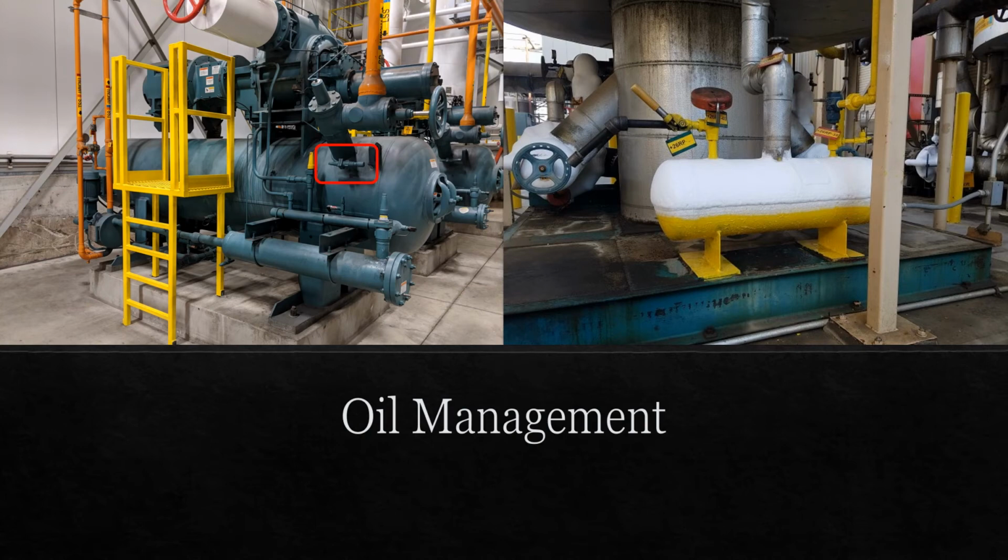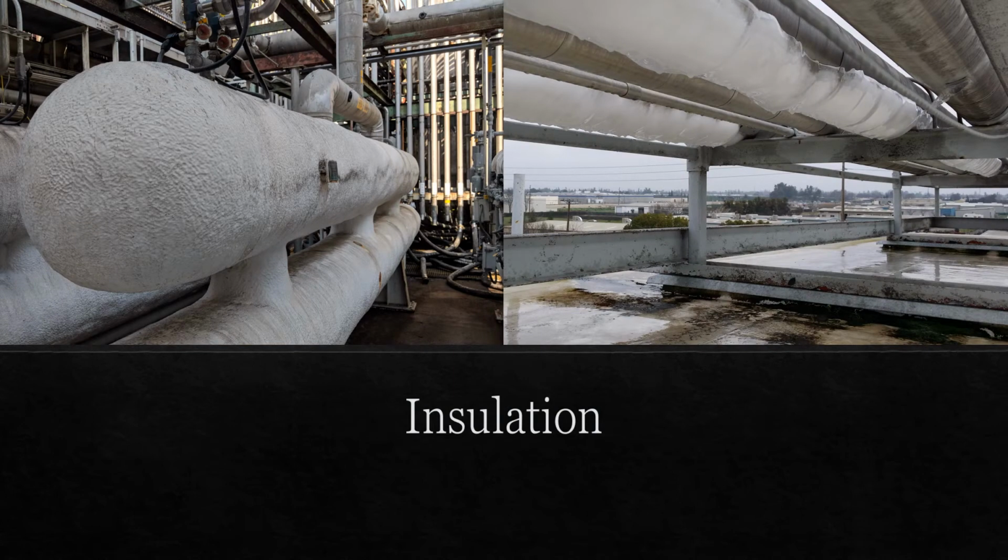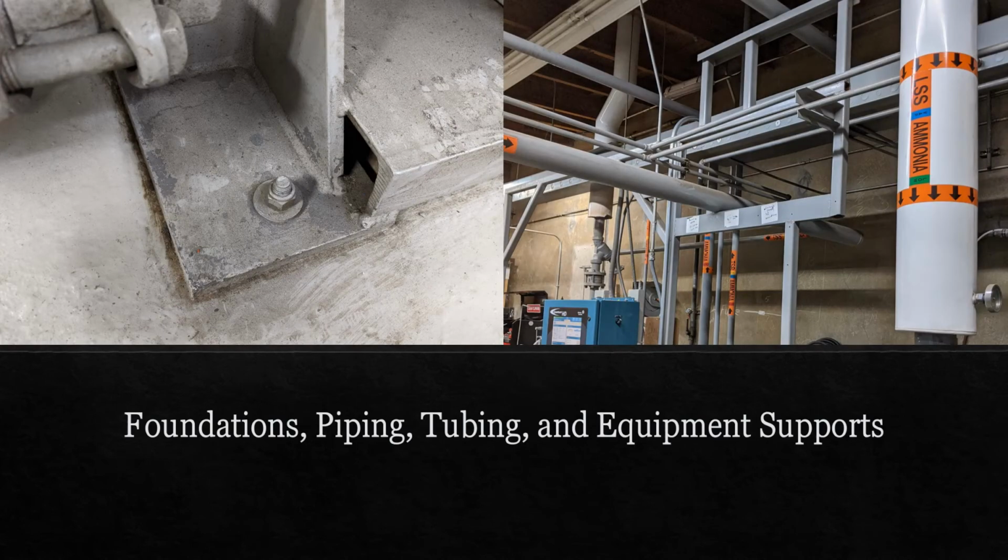Either is acceptable. Standard 9 requires that piping and equipment surfaces not intended for heat exchange be insulated, treated, or otherwise protected to mitigate condensation and excessive frost buildup. This section exempts valves and other equipment from requiring insulation where insulation would restrict access to the component. Also, pipes and fittings constructed of corrosion-resistant materials or protected with a corrosion-resistant treatment need not be insulated so long as they are routinely defrosted to limit ice accumulation.